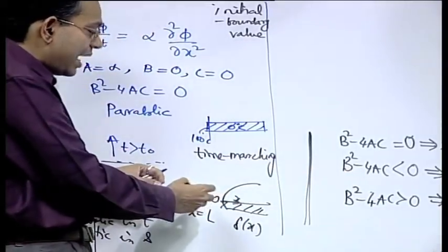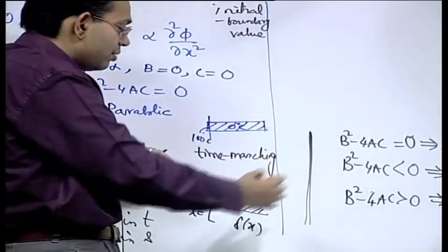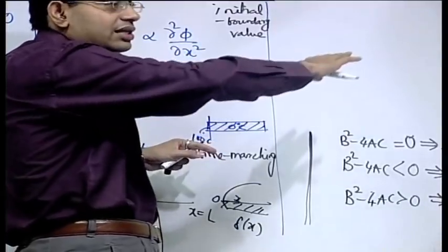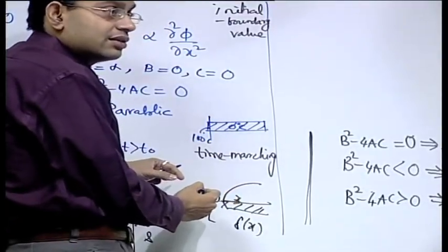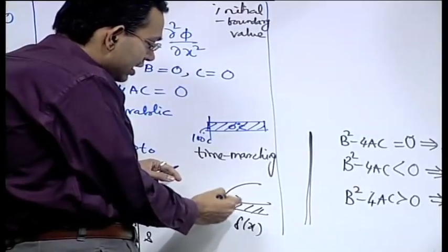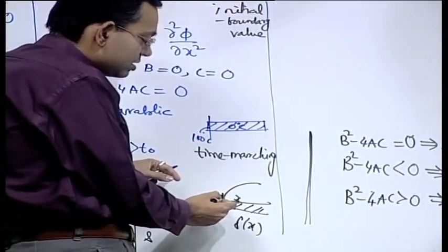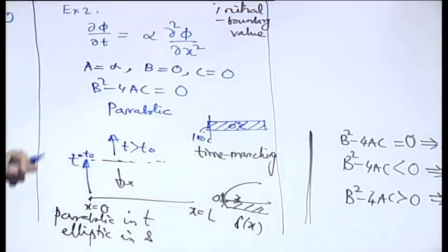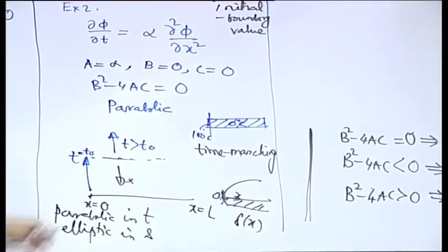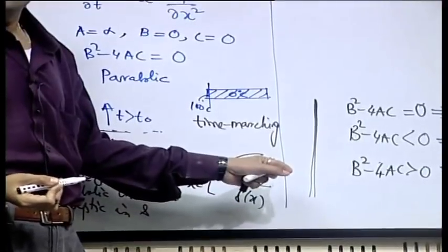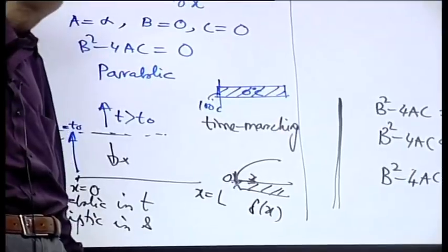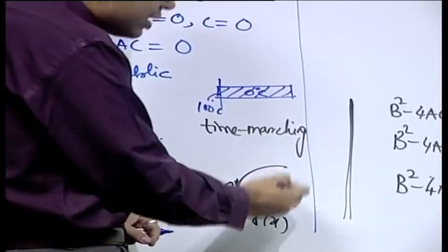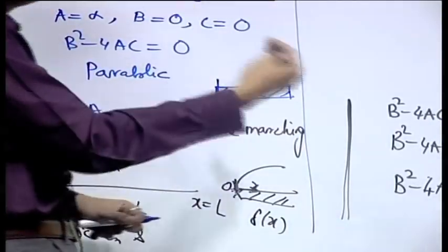Of course, practically the plate is bounded by a finite limit, but in principle you can go up to infinite length along x, but you cannot go to negative x. So, your origin of the problem is starting from x equal to 0 towards open infinity at x tends to plus infinity. So, that is like a space marching problem, that you are marching only along positive x, and whatever is happening at some x is not influencing what is happening in the back.